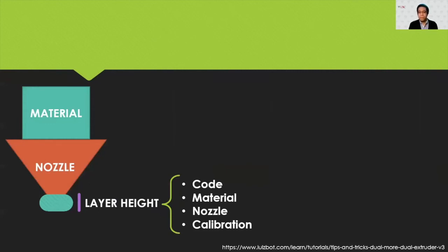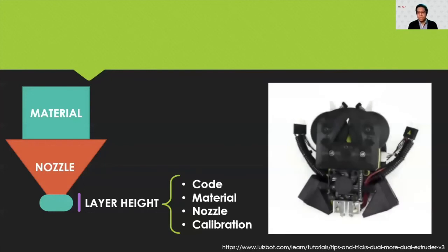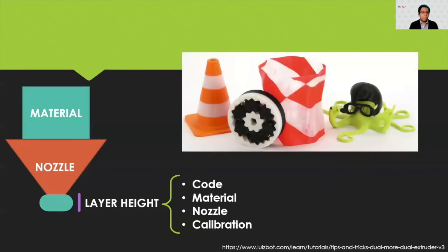Different printers allow us to use different printer heads, and consequently different materials. Here we can see a head that can extrude 2 filaments without needing to stop one print to change them. This is useful not only to have different colors in a single print, but also to use 2 materials with different properties.